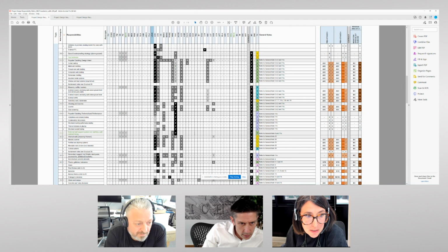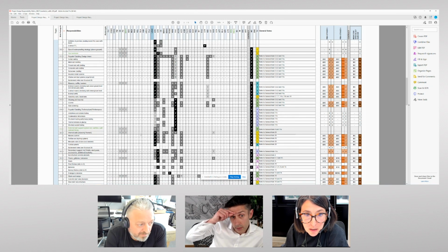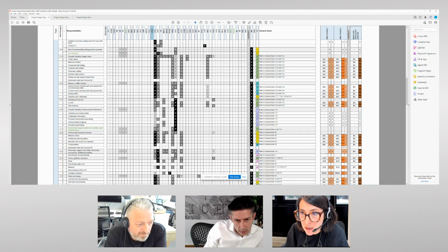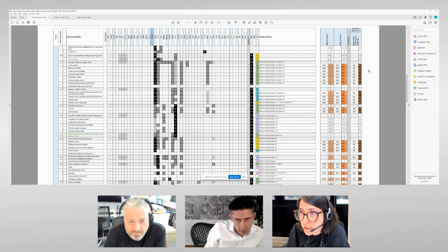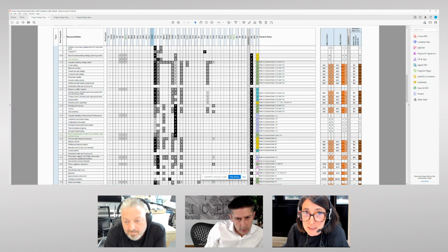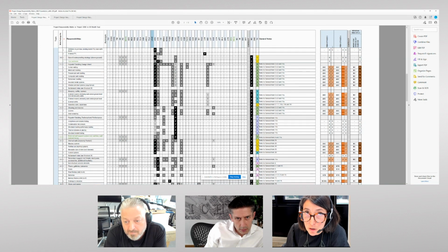So for internal walls, the architect would take primary responsibility in this particular project, and the level of contractor responsibility would be level C. What you also can see on this extract is that we use the DRM to define the levels of detail and the level of information that's contained within the model to ensure we're using our template to do as much work as possible to ensure that there's no scope gaps.